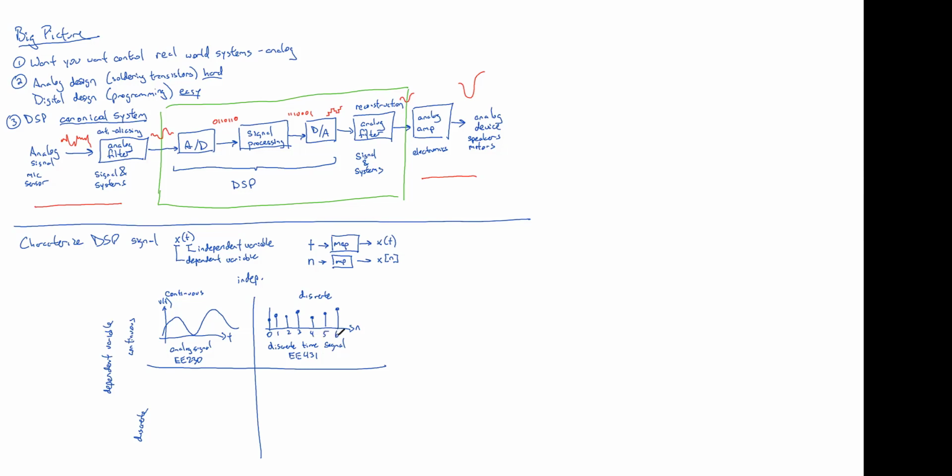The vertical scale can be anything. It can be continuous, but the horizontal scale can only be discrete. Realize for a second that that allows you to store this signal. Instead of continuous time, which has to be done graphically or as an equation, this can be stored as a vector of values: 1.2, 1.56, minus 6.3, and so on. That's stuff that MATLAB can work with, and that your microcontroller can work with and process.